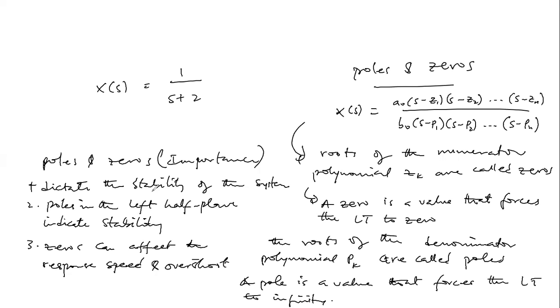So now that we have this expression, by the time we set the characteristic equation, which is the denominator, so when you get to control studies and all of that in your higher studies, you'll see this is the characteristic equation. This is very important. With this, we're able to tell if the system is stable or not. So when we set the characteristic equation to 0, we're able to derive the pole. Now, if we equate the numerator to 0, we're able to get the zeros.